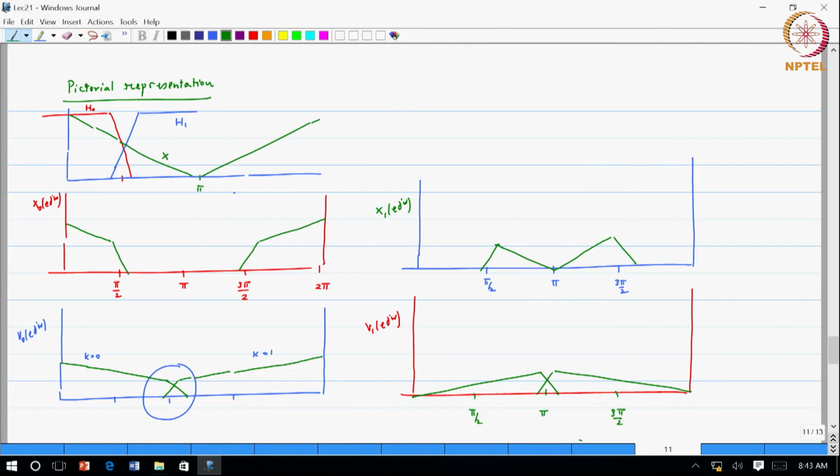if you were to remember how we did the downsampling, what did we do? We first replicated by shifted versions of it and then stretched it. So, if you do the shifted version, you will get a copy of the signal here. So, you will get a copy of the signal which is here for the shifted version, and then you stretch it, that means then that is when you get this portion. Okay. So, be careful when you do the downsampling of a band pass signal, you have to make sure that you get the correct scaling of the frequencies.